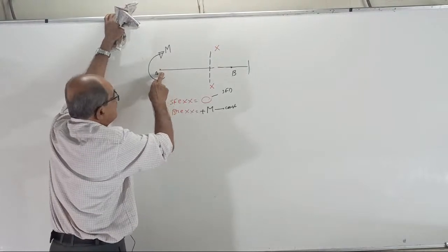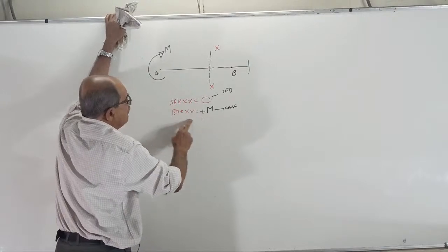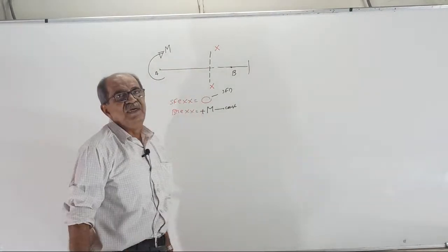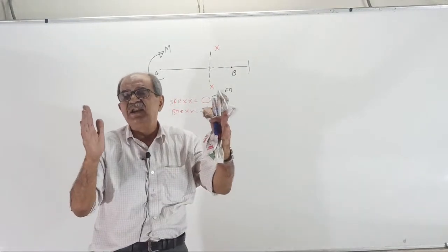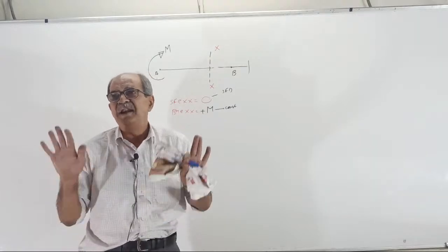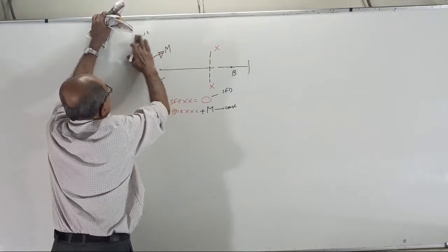See, that is the next one. When no shear force is there, the shear force diagram is not there, and BM will be constant, so it will be a rectangle. This is called constant BM for that entire region, or there is a name called pure bending. These I discussed earlier. Okay, take. Now, this is the first case.